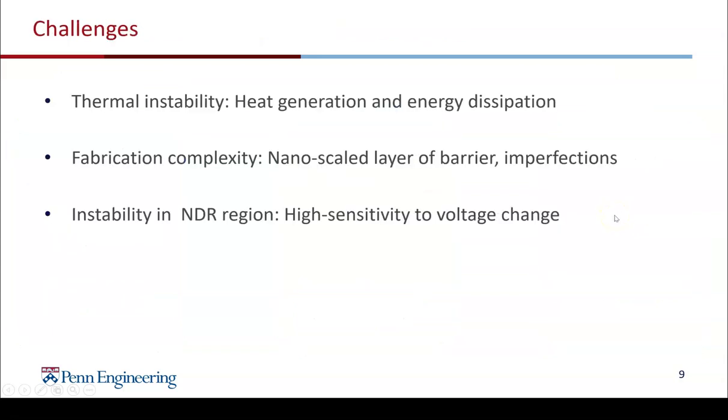However, we still face some challenges. The first challenge we are facing is thermal instability. At high frequency, the RTD can generate significant heat, since some electrons overcome the barriers not by tunneling but by thermal diffusion. The second is difficult fabrication.